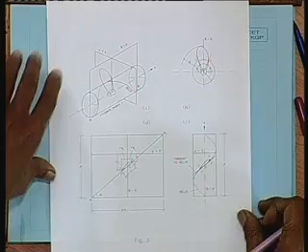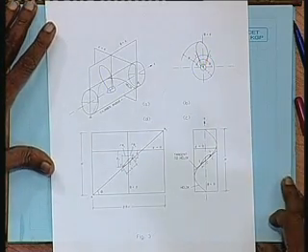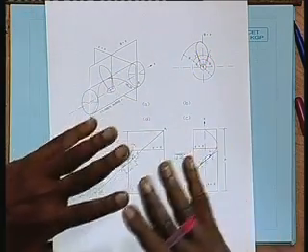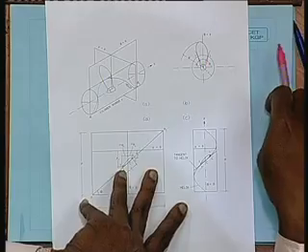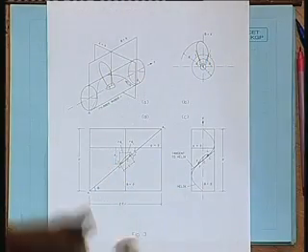Now, let us look at this. Propeller geometry is actually very interesting. It is a highly three-dimensional geometry, the face, and the propeller face forms a part of what is called a helicoidal surface. Now, what is a helicoidal surface? We already mentioned that it forms a part of the screw surface.